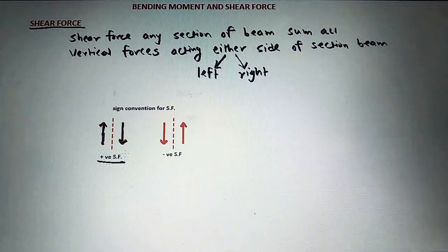Again see here, this is a section here, and the vertical force which is acting on the left side of the section is in upward direction, and the vertical force which is acting on the right side of this section is acting in a downward direction, then the shear force should be considered as positive.